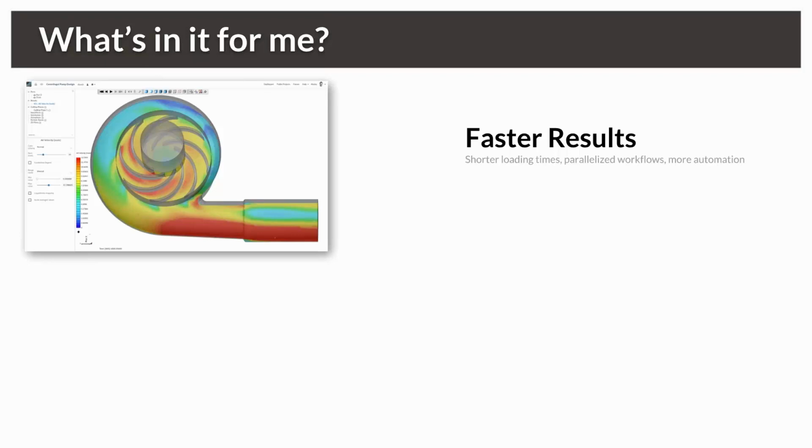Last but not least, you've seen some of the first steps towards more automation within SimScale, such as, I'm changing the turbulence model, all my prior settings are being maintained. I'm changing from steady state to transient, all settings that make sense in the new simulation setup are being maintained. I'm adding passive scalars, and so on. All of these changes do not need to be redone by the user. Same when switching the mesh, I do not need to reassign anything. So more automation in the general workflow.